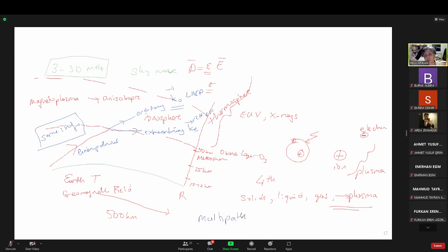And as the wave propagates, they are going to have different polarization differences. Now I'm going to explain how they exit from the ionosphere. When you sum them up over an antenna system, they're going to have these phase differences between them, and your original linearly polarized polarization will be rotated. It's called Faraday rotation. So your polarization plane will be shifted.